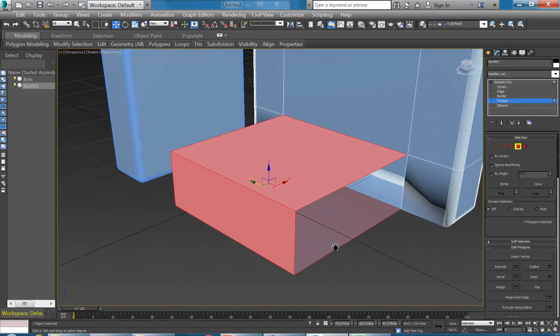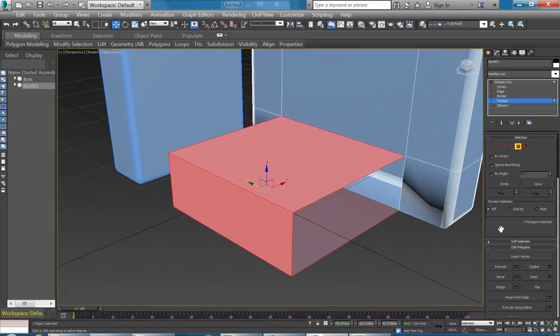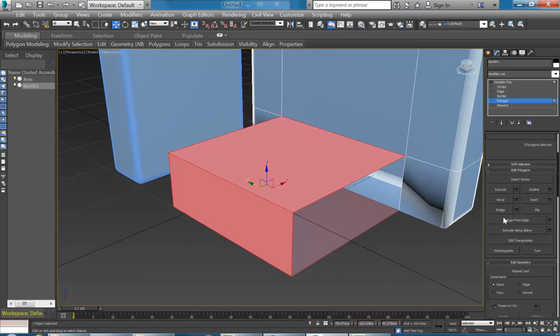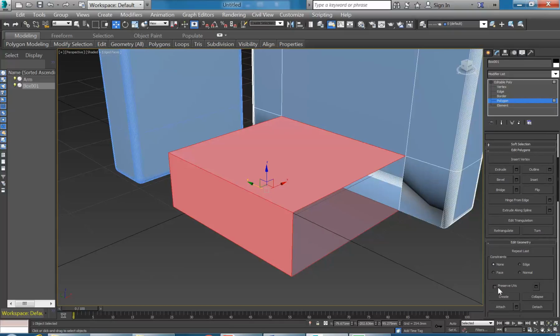I could use cap, but you can also go and manually create faces. And so why can't I see the option? Here we go, create. And the trick there is just to draw clockwise. So you can easily draw in your own faces. And I missed one. Let's do that again. So click, click, click, click.